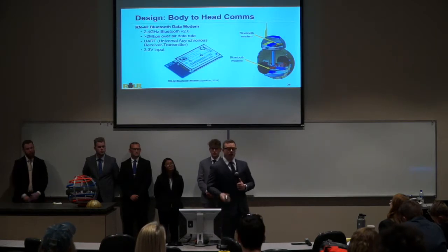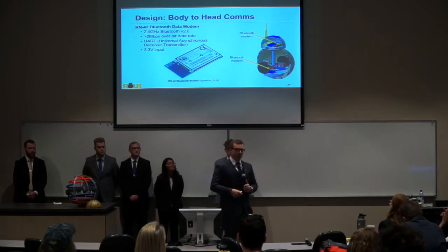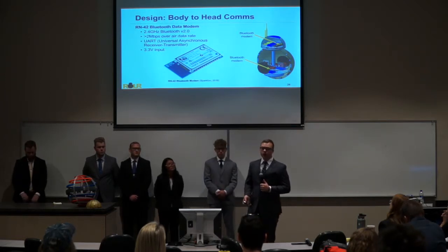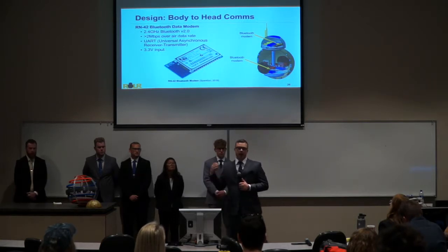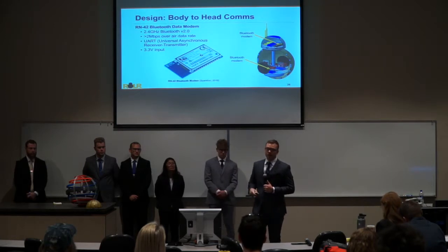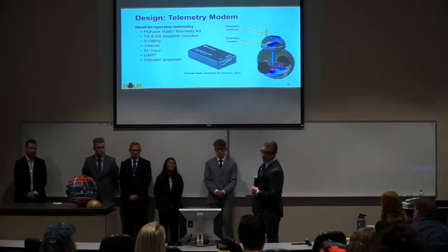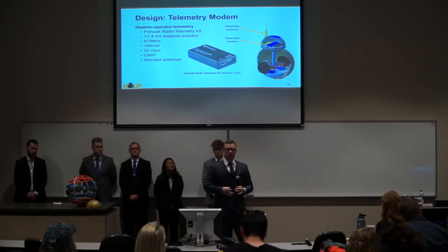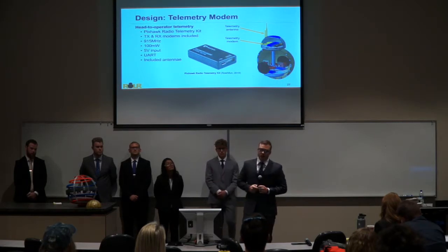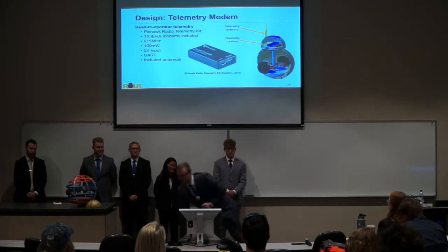Since we don't have any electrical connections between the ball module and the head module, we need a way to easily facilitate data transfer between the two. For that, we've gone with some low-power, low-range Bluetooth modems, again, just because they're so easy to work with and they have good documentation. They can take a UART standard serial data input and transmit that over Bluetooth up to the head, where the rest of the data is concatenated and then sent out to the operator using the telemetry modem. This telemetry modem again takes all of ROLR's operational and scientific data and conveys it back to the operator over 915 megahertz.